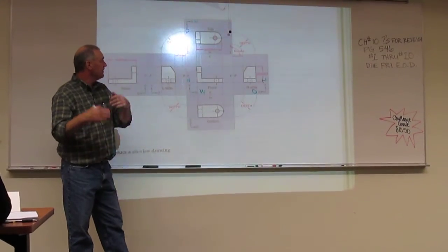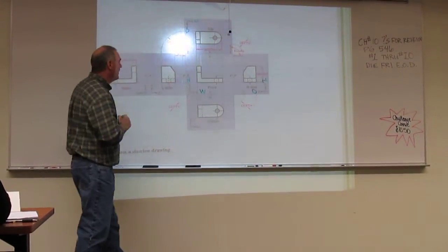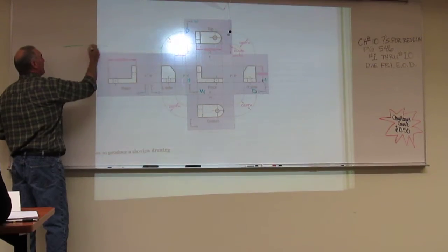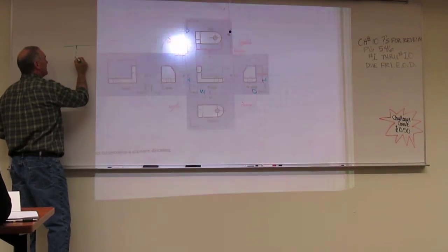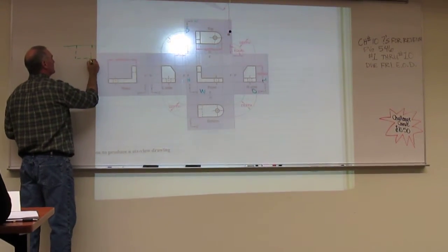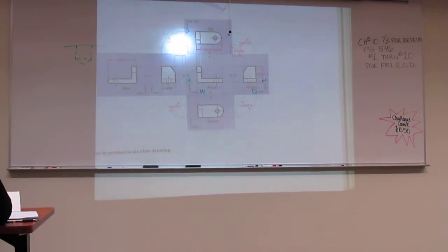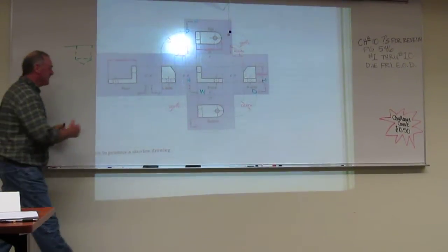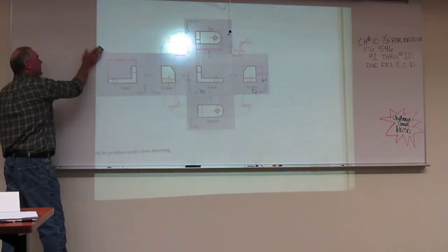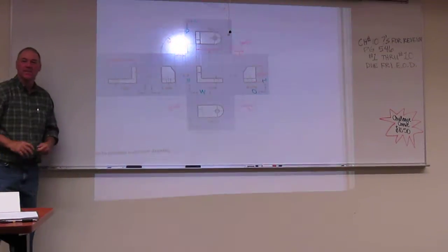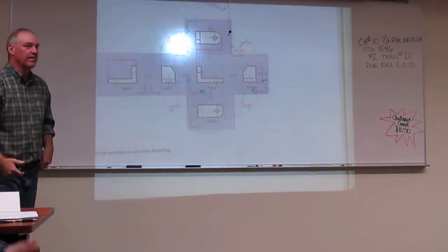Actually, you're kind of jumping into our third lecture here, but you do have what's called a blind hole, and it will look like this, okay? And it will look like that. We call this a blind hole. A blind hole is one that doesn't pass all the way through an object. So would you have to show the bottom? Oh, yeah. We've got to tell them the hole stops, or expect them to drill right through it. Yeah. And there are techniques we use in the dimensioning and display process to make sure that that happens. And it doesn't require additional views.